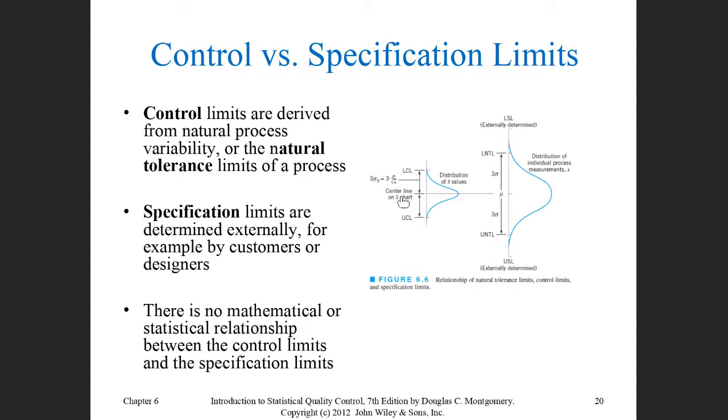Your control limits, in the best case, if you have done your design very well and you run your process, when you gather the data, the ideal case is for the control limits to be even less than the natural limits, which are also less than the specification limits.